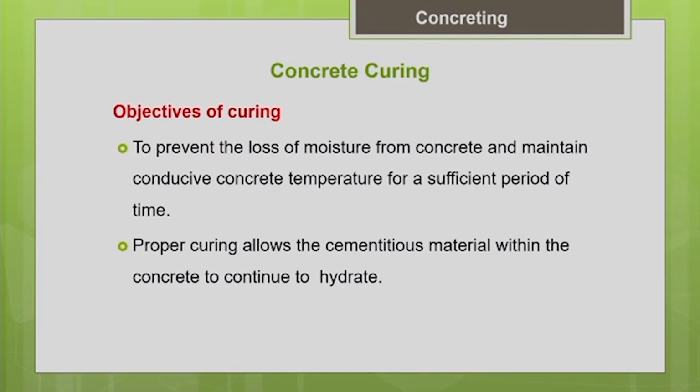After the finishing is done, after the concrete has attained the final setting, the traditional way is to supply water to concrete and facilitate the continued hydration process. The main objective behind the supply of water is to prevent the loss of water from within the concrete to the outside environment, as well as to supplement the lost water.